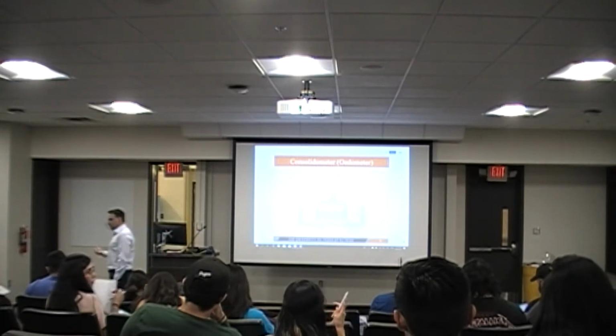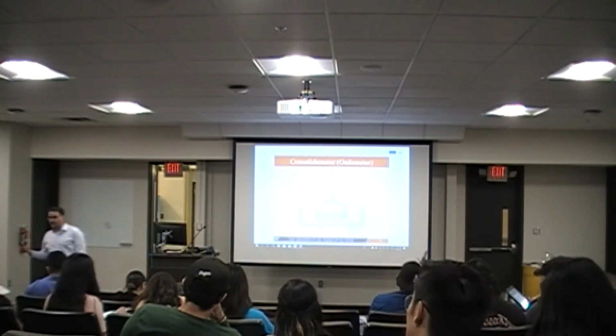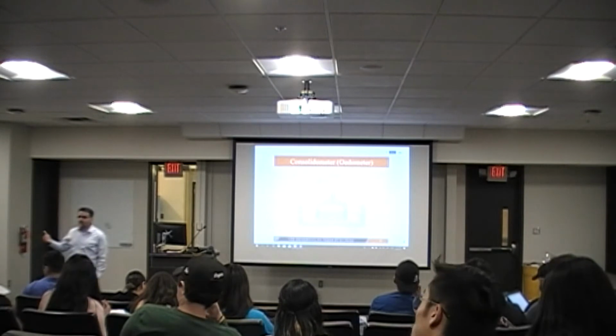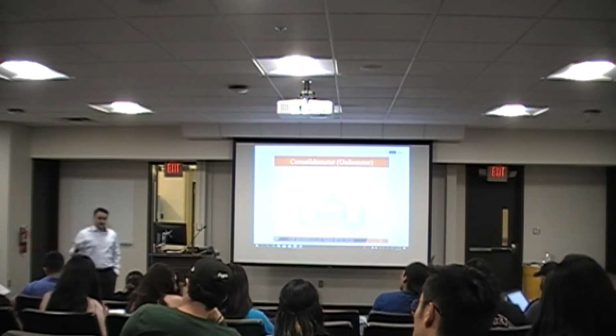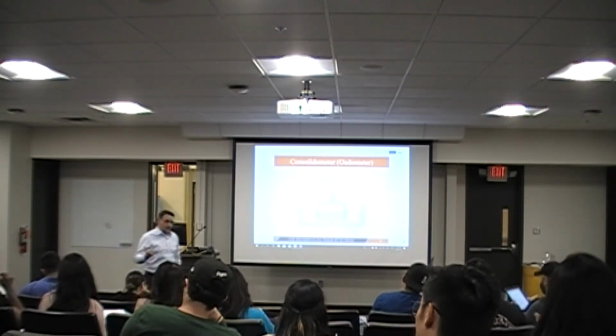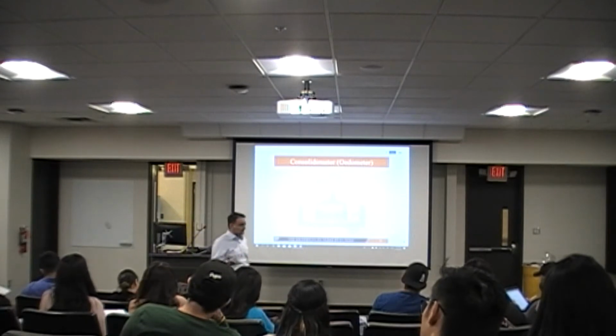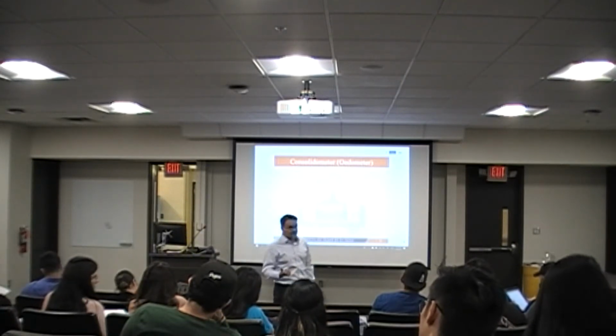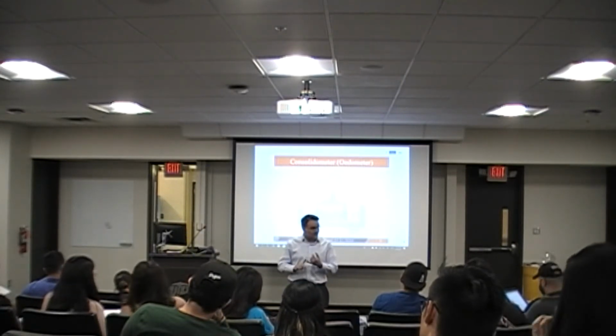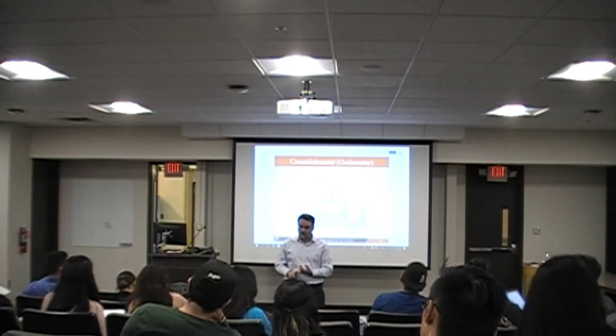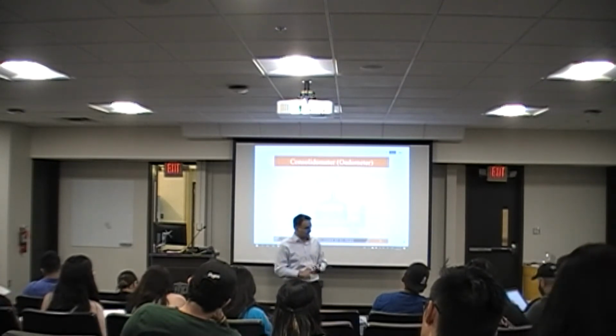What was the characteristic of that? There were two important things there, Julio. One of them was that the layered elastic theory, or theory of elasticity, is valid. What that means is that you can use that E value and mu value that we talked about in order to calculate the immediate settlement.